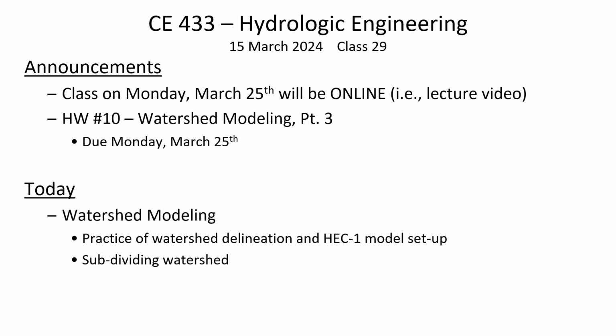I'm going to show you how you could do a lot of automated simulations with a variety of different precipitation depths and a variety of curve numbers, and how to probe at some of the uncertainty that can exist when we don't really have precise knowledge of how much precipitation there's going to be or what the curve number is. We just sometimes have estimates of those things. It allows you to develop the range of possible flow rates rather than just assuming a single flow rate that you're going to get.